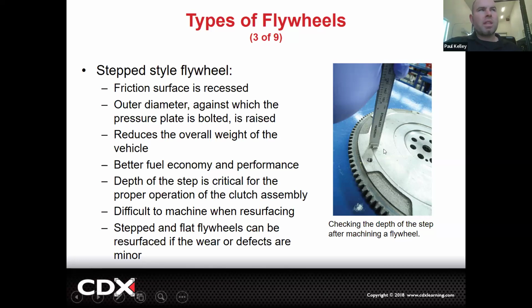But other things that could make that clutch disc slip is the clutch disc is just worn out. Maybe the spring, which is part of the pressure plate, clamping the disc is weak, and that's going to make it slip. Maybe you have a massive rear main seal leak, and that's running oil down on this flywheel, and that's going to make it slip, right? So there's a bunch of stuff that'll make this piece of junk slip. Maybe you have a very glazed, super shiny friction surface here on the flywheel and on the pressure plate. That would also make it slip, right? But let's go back to the release system.